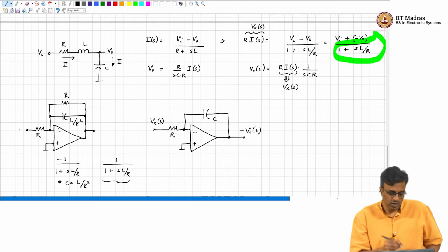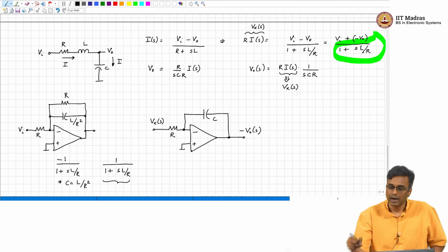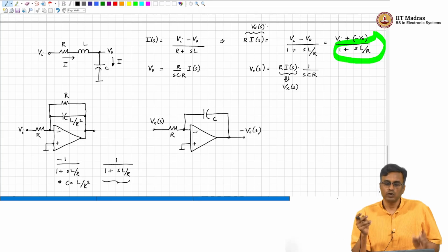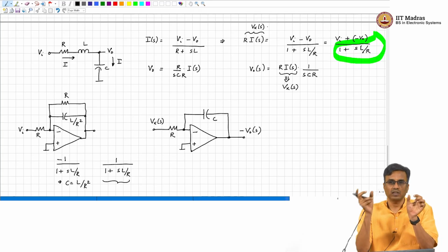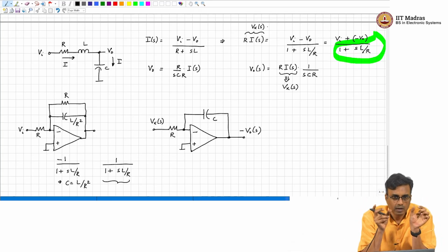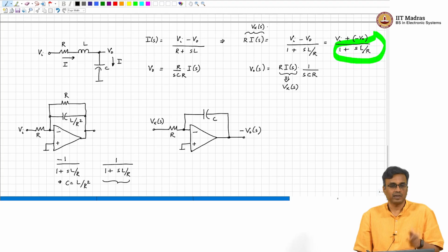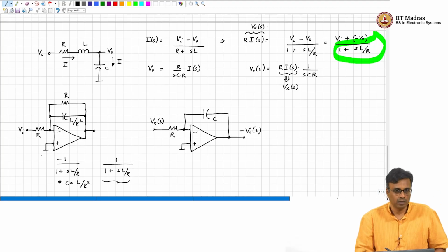Okay, so this is Vi, and to this we must add minus V naught. So, what should we do? To generate Vx, we need to add Vi with minus V naught and then low pass filter that result, correct. The low pass filter is here as shown on the left.